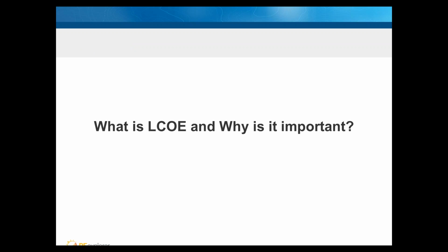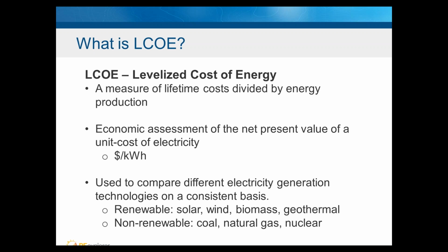What is the LCOE and why is it important? LCOE, or levelized cost of energy, is the measure of lifetime cost divided by energy production. It's an economic assessment of the net present value of the unit cost of electricity. A common unit of this is dollars or the currency divided by the kilowatt hour, or megawatt hours if the scale is bigger.